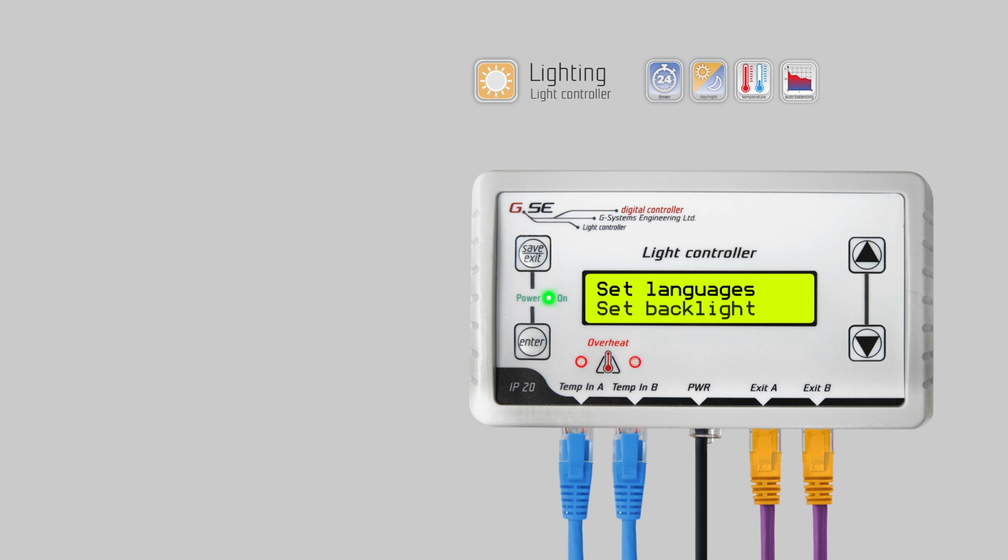Set your display backlight to on, off, or automatic. Automatic mode will switch off the backlight, and return to the main menu after 1 minute of inactivity. As soon as you push a button, it lights up again. Set output type for both channels. Here you can choose between 0 to 10 volts, or PWM signal, depending on the devices you have connected.